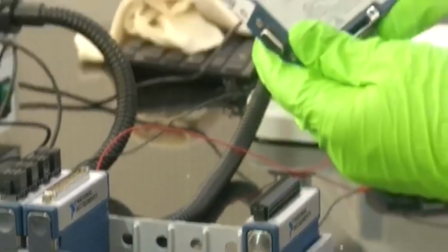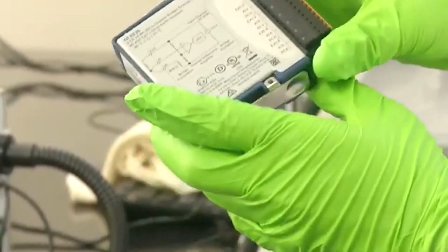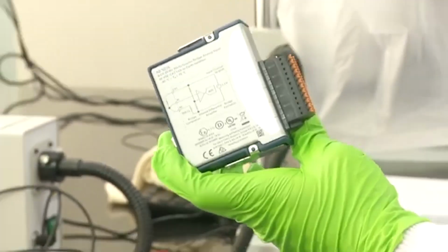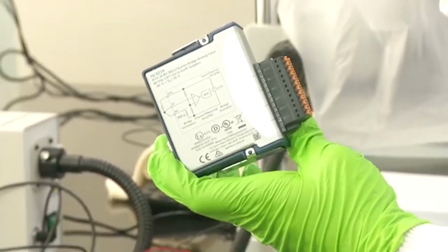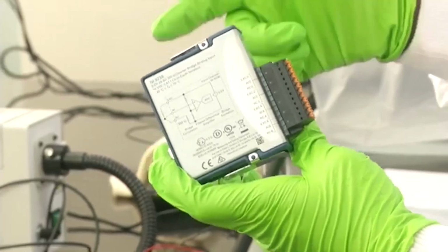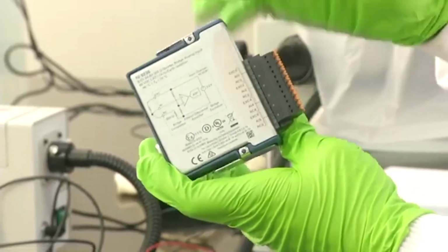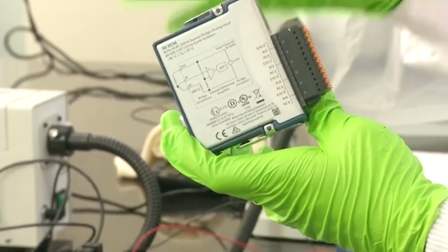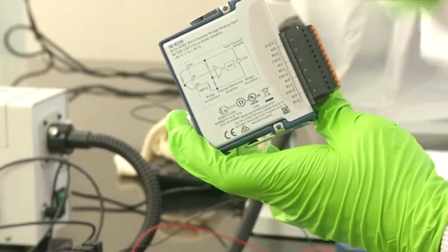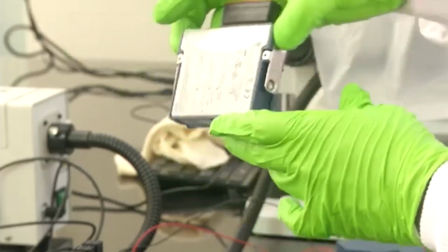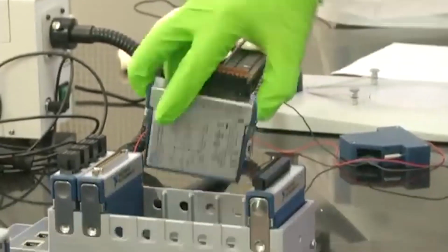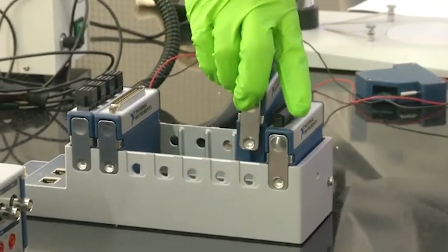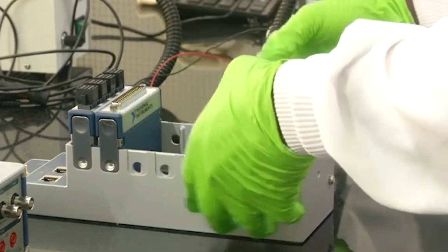The other one is a quarter bridge analog unit. The difference between the previous module which I showed and this module is that with the previous module, you can perform a quarter bridge, half bridge and a full bridge. But with this module, we cannot perform half bridge or full bridge. This is only meant for quarter bridge applications. I can place this on the chassis too. Just simply plug and play, very easy to connect.